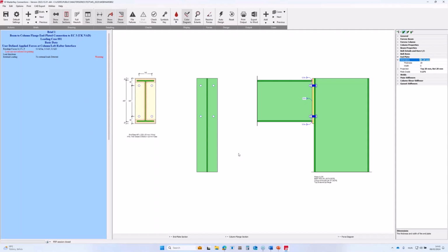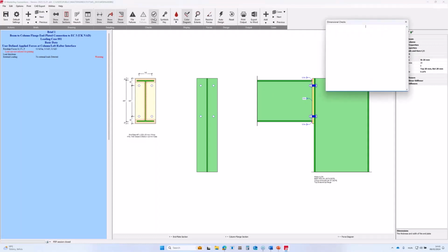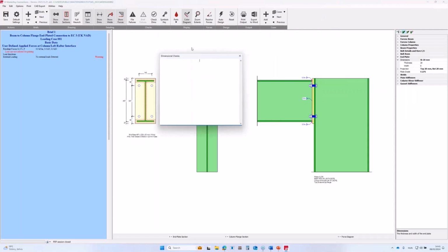The program not only checks the design rules, but the detailing rules as well. So in case of any detailing issues, the background of the graphical area turns cyan blue, and the check dimension screen gives you a detailed description of the problems, but it's empty now. Good.